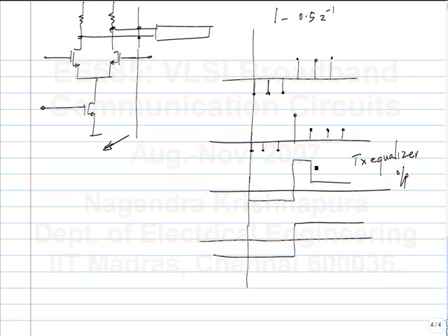So how does this help you? There are various ways of thinking about it. I know that this already is a high pass response, so it compensates the low pass response of the channel. Another way to think about it is, let's say I had a first order RC filter to which I am passing this. So if I had this step, it would rise up as an exponential slowly. Now by introducing this overshoot, I am kind of aiming high during this period, right?